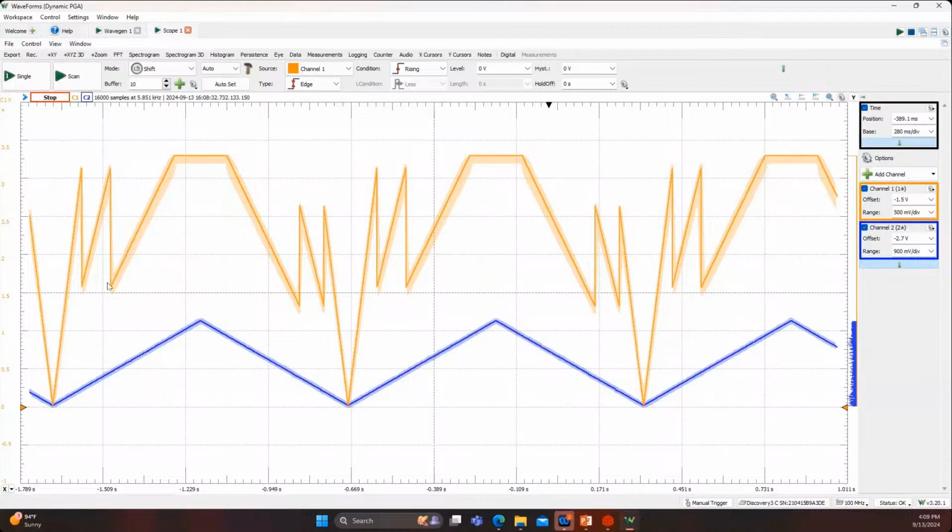And then once you hit the minimum programmable gain, which is 2 for the system, it will continue to increase until you rail out at 3.3 volts and stay consistent there. Then on the way back down, as the input signal decreases, you will continue to decrease your op-amp output until you hit the window comparator minimum.